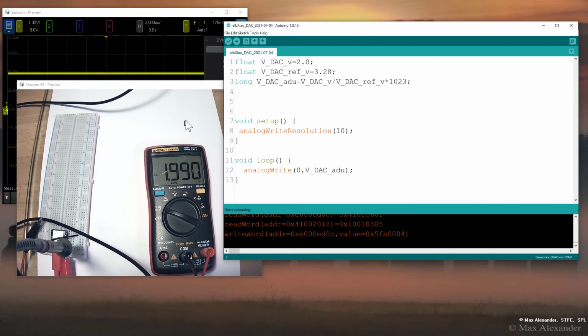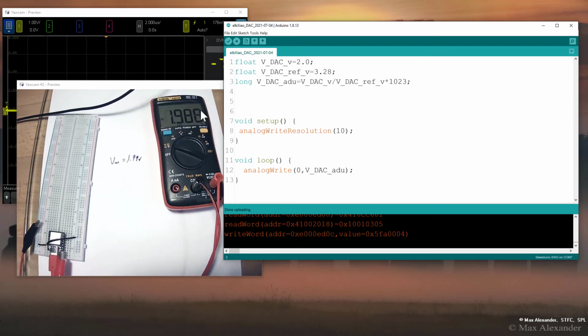Now, the one last piece of information we'd like to get is, hey, what's the output resistance, the Thevenin resistance of the DAC channel? Now, generally, the DAC channel is not going to be able to drive a lot of current. The spec is typically about 7 milliamps max current. And so if I put my 100 ohms here, I'd get 30 milliamps of current. This poor DAC is not going to be able to drive that. Let's try the 100 ohms.